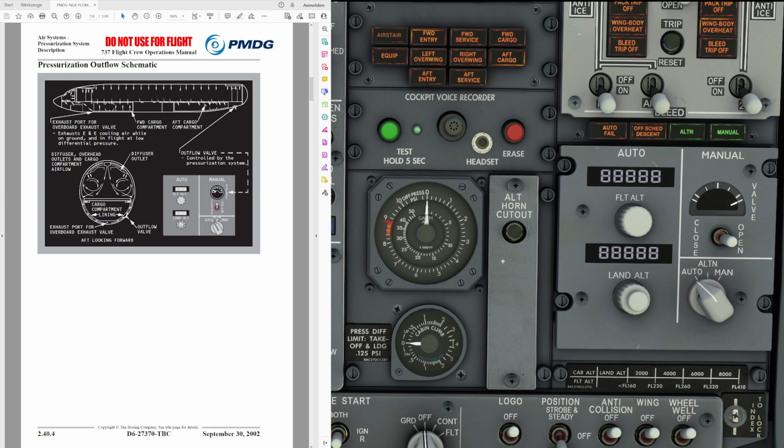Be aware that according to the Boeing checklist instructions, it is permissible to execute any checklist from memory, provided no hazard is created. So if you're in a descent and the off-scheduled descent light illuminates, it is permissible for you to reset the flight alt to the present altitude without having to get out the QRH and carrying out the complete checklist. And that is then going to restore normal system operation. And be aware that this capability is lost when the flight alt indicator is changed in flight.